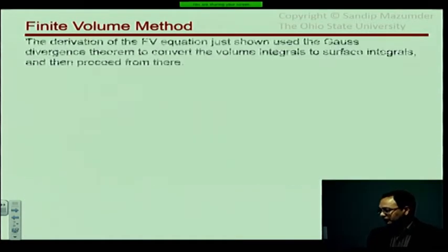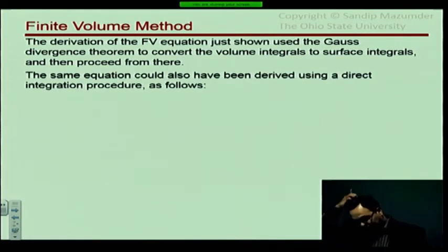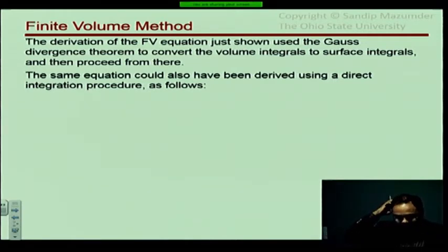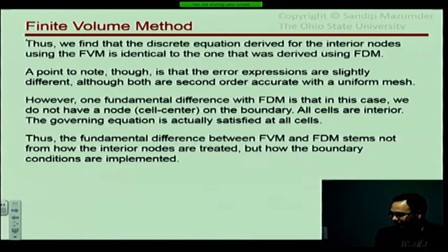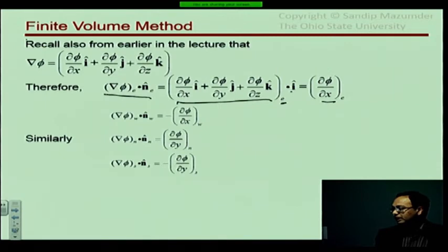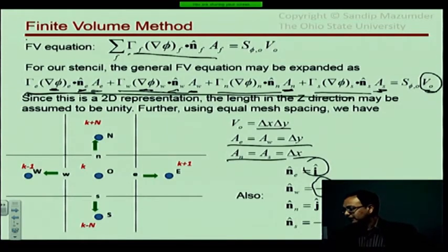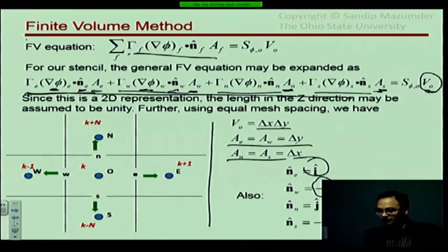Boundary conditions. So the derivation of the finite volume equation. Before I talk about boundary conditions, I have a couple of slides here to show you a different viewpoint. By that I mean here up on top we applied the divergence theorem to get this equation, and then we reduced it using our particular orthogonal stencil, and then figuring out all the terms and plugging it in.